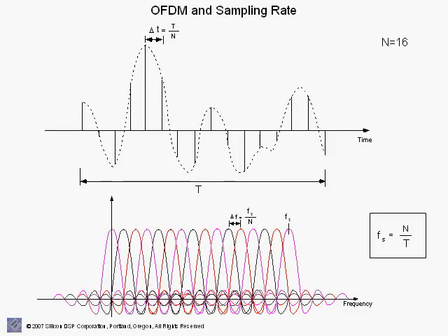A major part of this tutorial is the fundamentals of OFDM, and we will go into detail on OFDM and how OFDM is used in order to provide reliable and robust communications over multipath fading channels. We will describe how OFDM achieves spectral efficiency and the orthogonality between the carriers, and we will actually derive the discrete Fourier transform formulation of OFDM, and we'll also discuss the FFT as used in, for example, the demodulation and the inverse FFT for the modulation of OFDM signals.